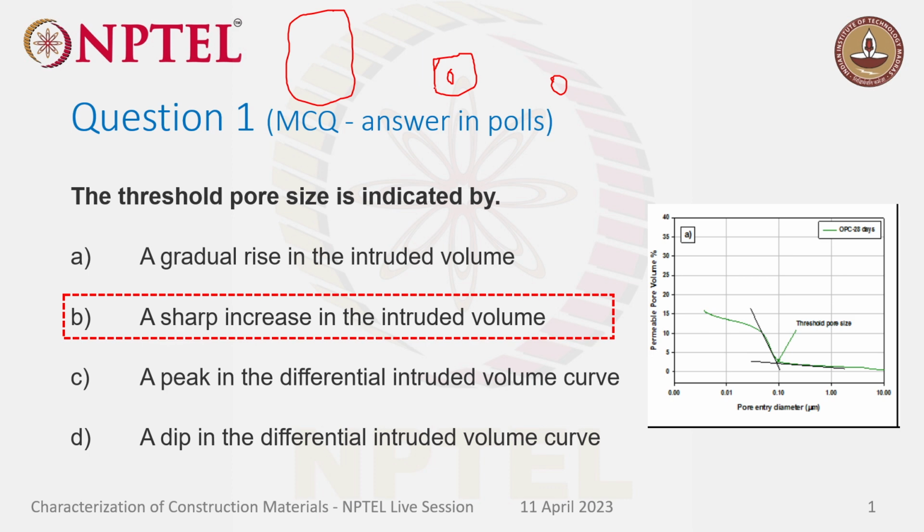See, when it comes to the edges, wall effect can be there. When you compact the concrete cube, due to wall effect, compaction might not be proper. As you said, even if there is curing, if it's underwater curing, it's fine. But if it's normal air curing, the outer area might not be properly cured.